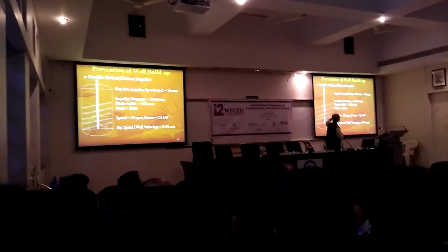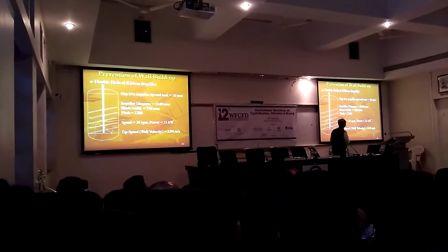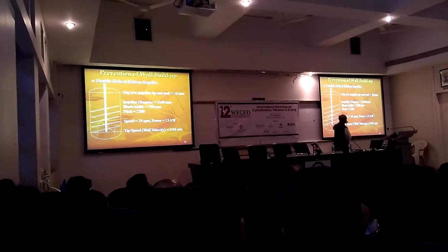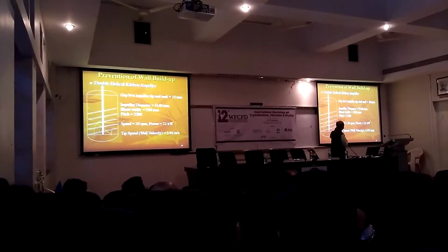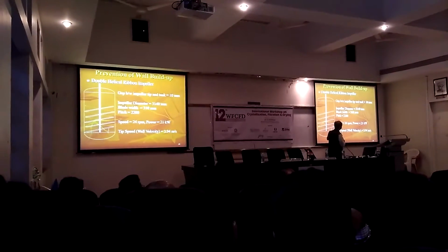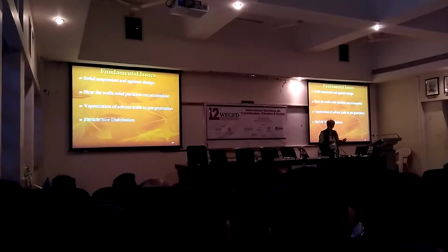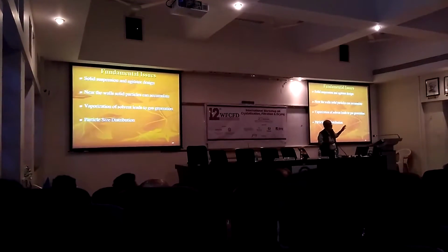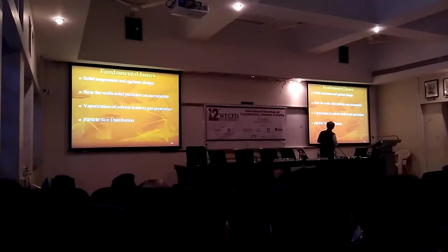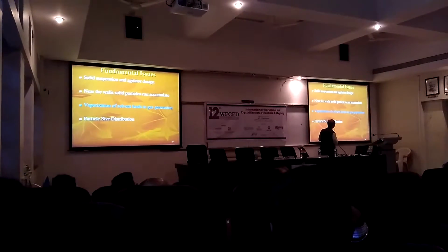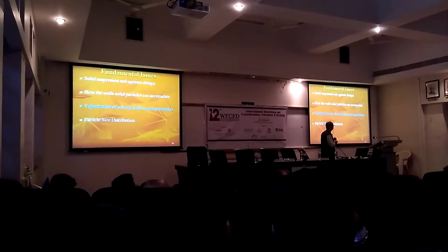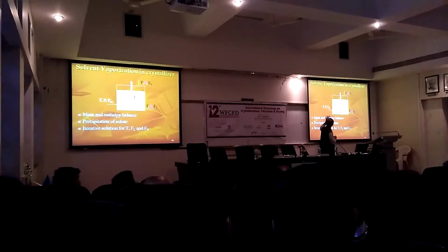Right, so this is again a typical case study which I have indicated out here, where the impeller speed which is required, impeller width which is required, the pitch which is going to be required, and you can calculate what is going to be the power number or power consumption for the type of design which you have finally zoned into. Vaporization of solvent leads to gas generation, and imagine this is the situation.